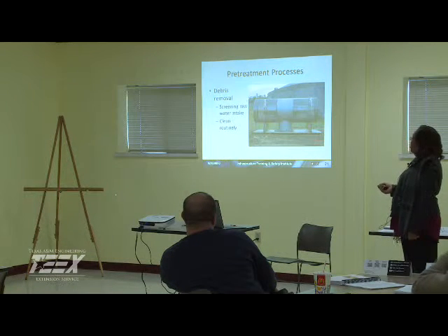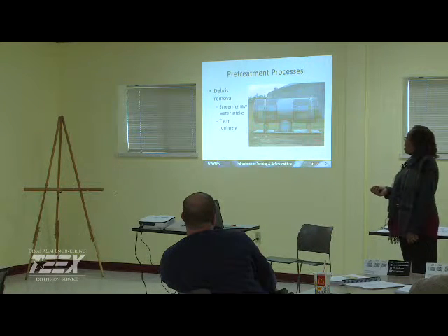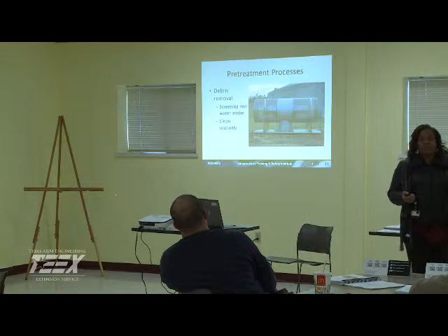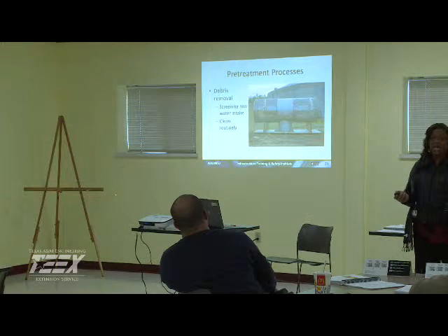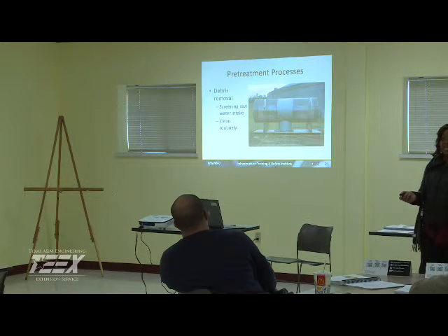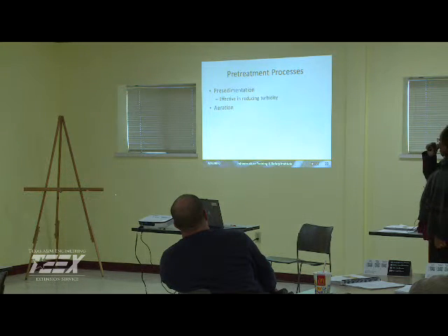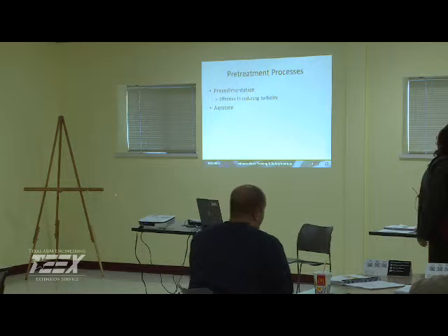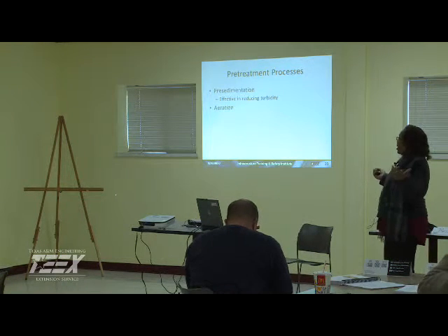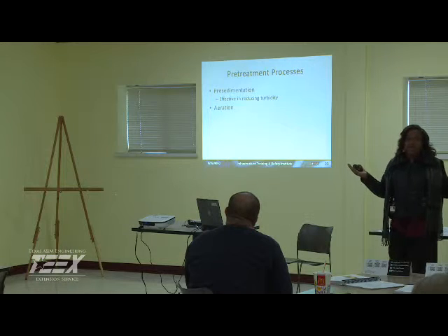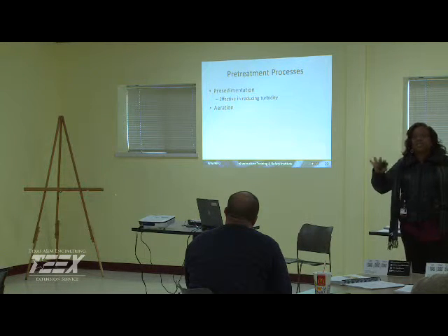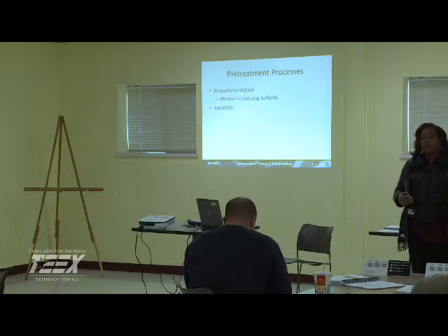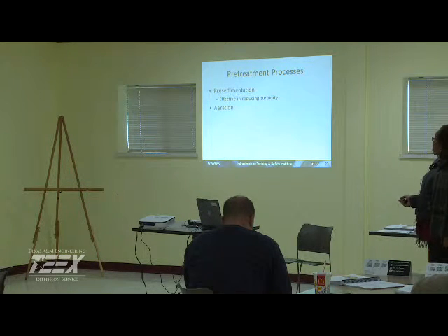Debris removal is another pretreatment process, and that can be as simple as providing screening at your raw intake. Now, if you provide screening, you want to make sure that someone is actually out there cleaning it manually or mechanically, because it can get clogged, depending on the size of the stuff you have coming through. Another pretreatment process would be something as simple as pre-sedimentation. Having a basin where things can settle out prior to introducing the water to your facilities. It's very effective in reducing turbidity.